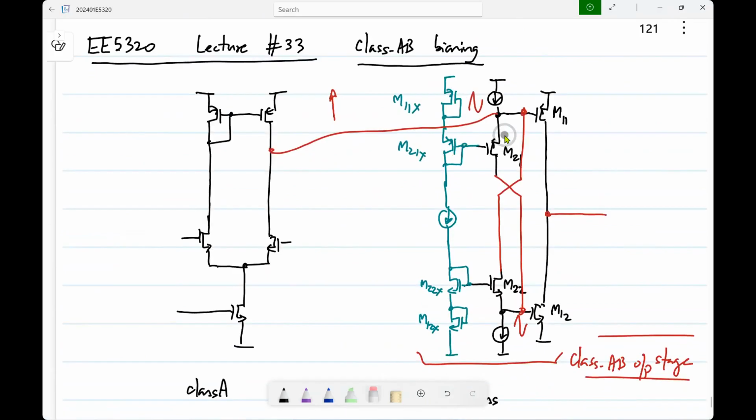See, early on we determined, like long back in analog circuits, that it is good to have a known current biasing through the MOS transistor, right? Because GM is less sensitive to transistor parameters. So we want to have a known quiescent current. Okay. Otherwise, you can just tie some voltage there and be done with it. So that's why we have this. It's basically a current mirror, somewhat fancy, so that we can also add a signal to that.